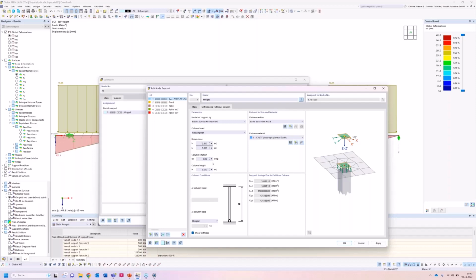We can say the dimensions of the column, 0.5 times 0.5 meters. It's again a really big column. I think the biggest one I saw was 0.4 times 0.4. But also we have not so many skyscrapers, so that's mainly the reason why I didn't have to plan much more. And yeah, now we have everything defined. We will go, there are also different possibilities. We will go with the elastic surface foundation as depicted in this figure, since it's just the best result.